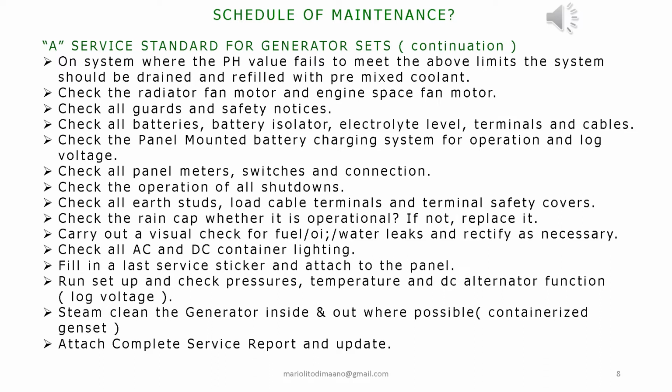Check all guards and safety notices. 4. Check all batteries, battery isolator, electrolyte level, terminals and cables. 5. Check the panel-mounted battery charging system for operation and log voltage.